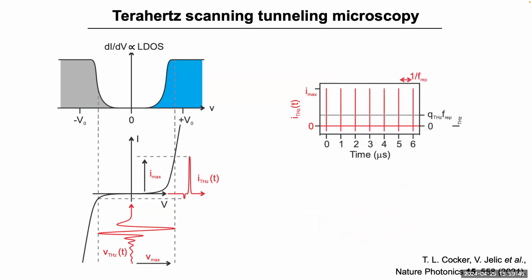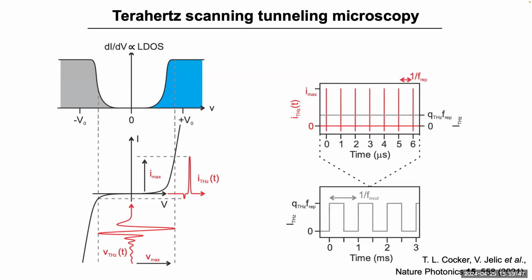Okay, and finally, what we actually measure is we have something physically blocking it, like a fan. It blocks and unblocks that terahertz beam, and we see that current turn on and off. And so we have basically some instrument that can look at the oscillating current, called a lock-in amplifier, and simultaneously we can measure the non-oscillating current, and we can do all this at once.